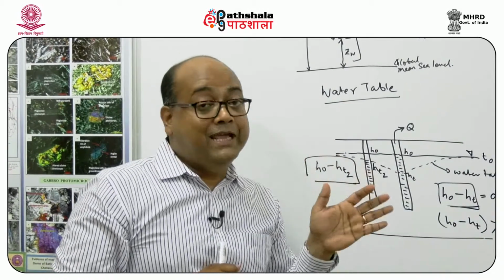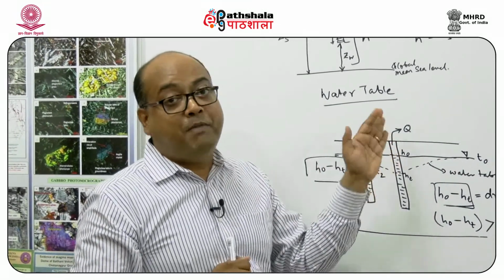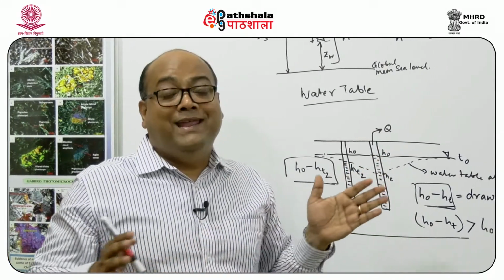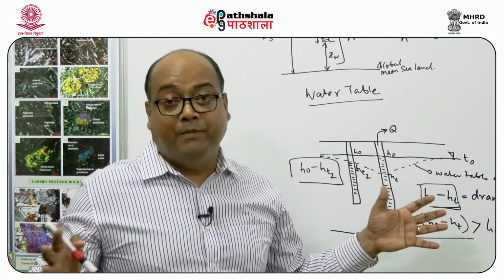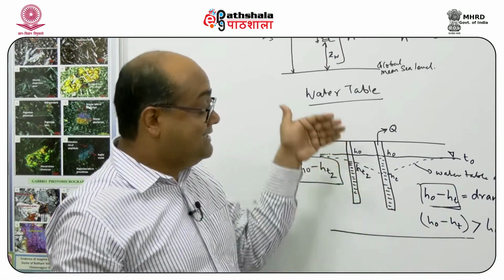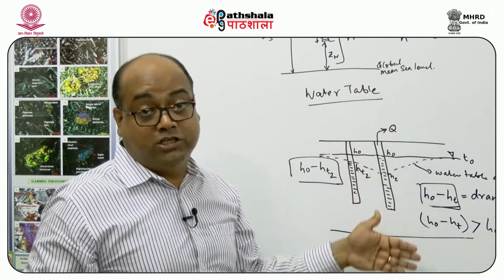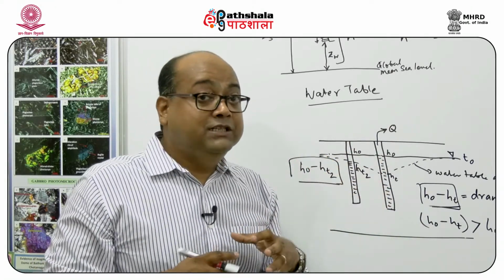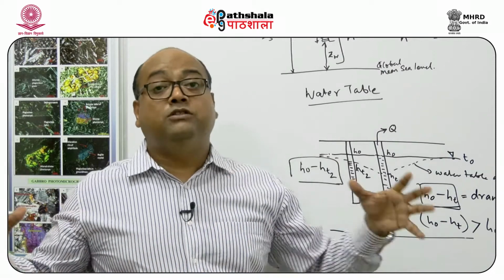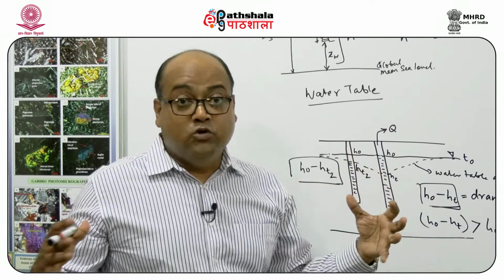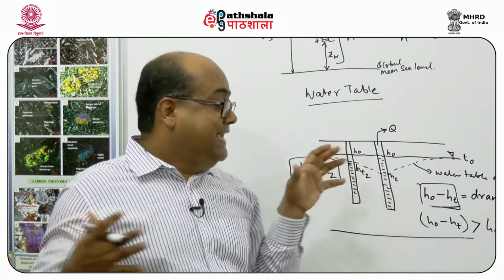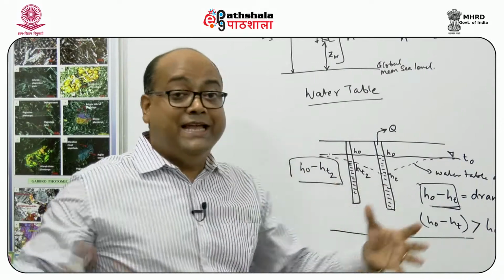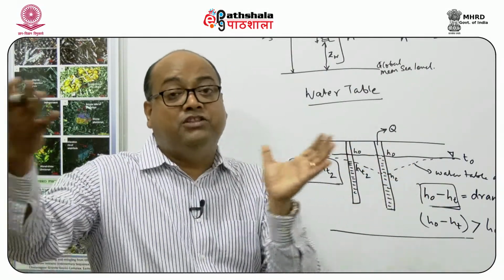What I'm trying to say is that the impact of pumping on the water table fades away radially as you move away from the pumping well. Now imagine this is a cross section of the land surface. Imagine extrapolating the whole thing into three-dimensional space. Instead of the depression appearing in only two directions, imagine it happening in three dimensions.